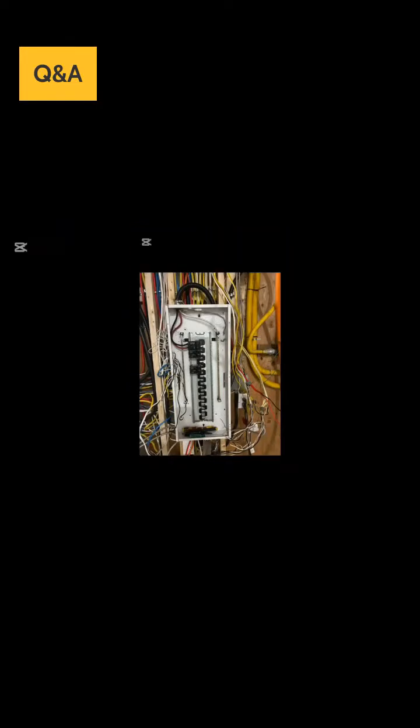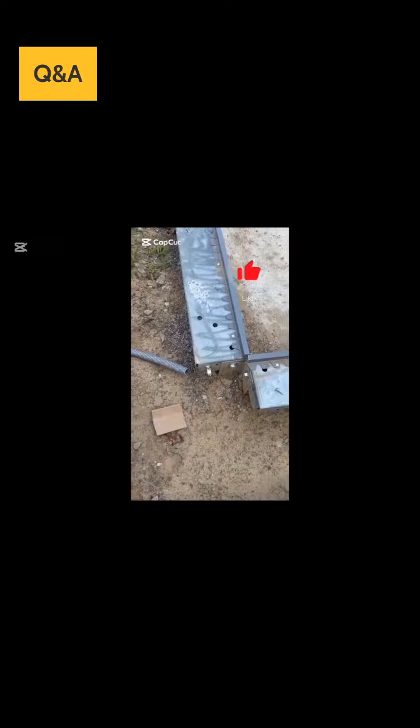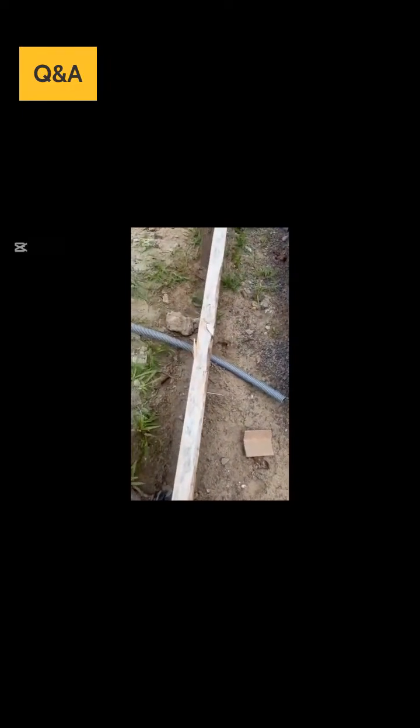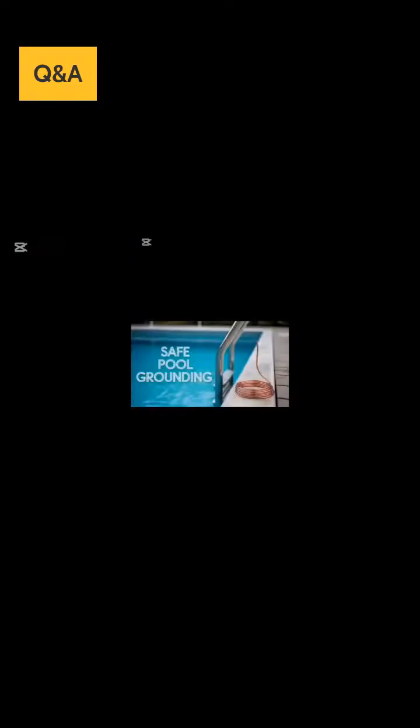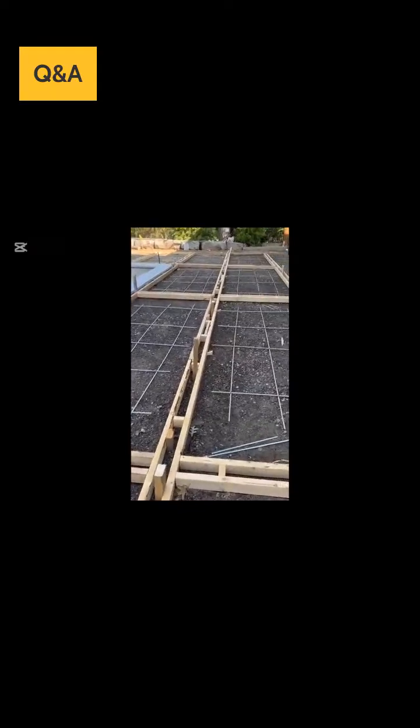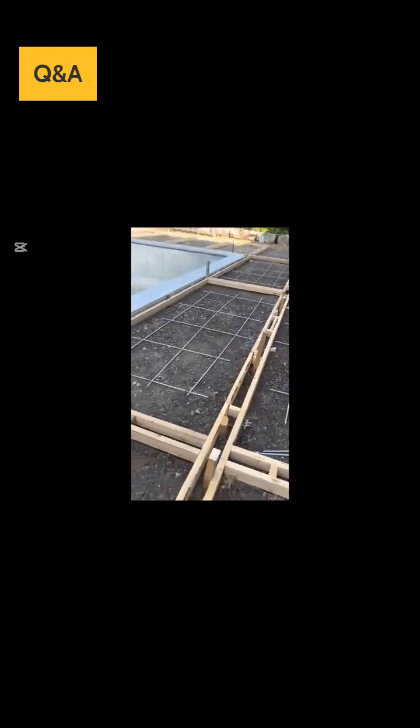Earth is used as a reference, and for lightning and surge dissipation. Code reference rules OESC 10-102, Rule 10-806, Rule 10-810. If you're relying on earth to clear faults, you're already wrong.